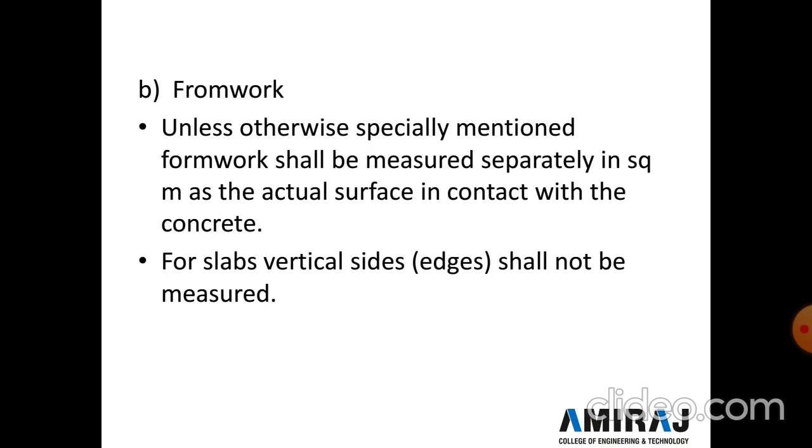Next is formwork. Unless specially mentioned otherwise, the formwork shall be measured in square meters as the actual surface in contact with the concrete. For formwork of a slab, the vertical side is not measured.